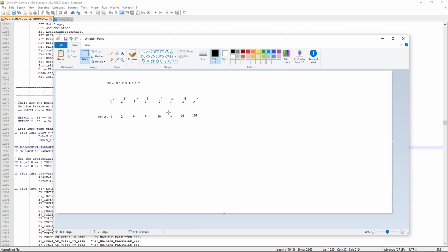You'll see various different parameters or logic out there, and depending on what you're going to use, bit-based might end up helping out. Now, another thing that could be done, rather than doing bits, is to have the PLC program say, whatever value is stored in 218, that's how many axes I have. For example, if the value is set to 2, it means I have 2 axes. If it's set to 4, it means I have all 4 axes. That can also be done. It's just whatever logic has to coincide in your PLC program for that.